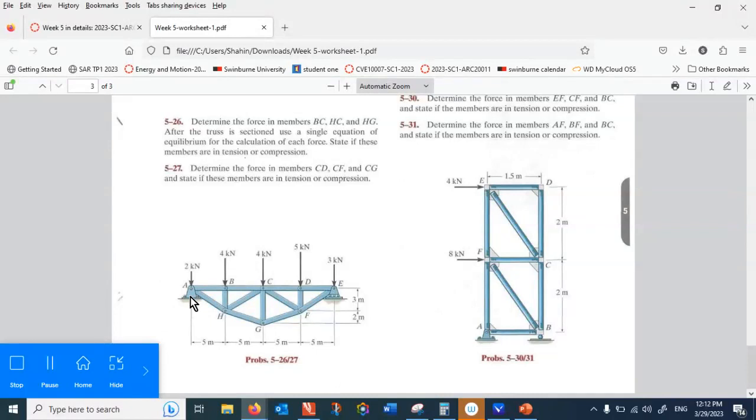Just the only thing which might confuse you is those external forces, they are different from the reaction forces. So you put them in the free body diagram and then exposing AY, EY, that is the free body diagram you have to solve. I think that's enough for today.